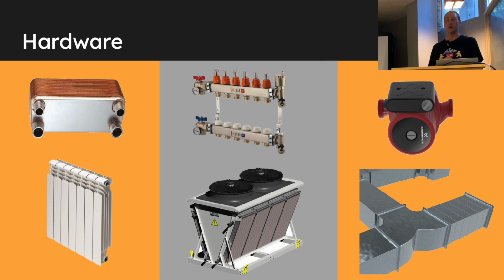So back to that high uptime discussion, if we wanted to reuse the heat in the winter but reject it in the summer, how do I reject it? You need a big dry cooler outside to send that heat away when you don't want it. And if you kept it in air, in the bottom right here, that's just your HVAC ducting.